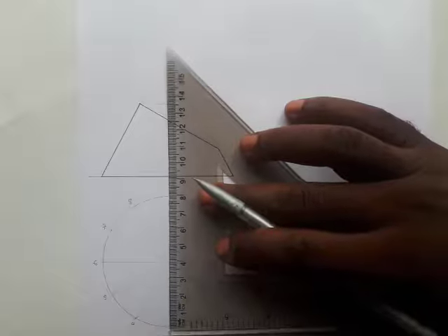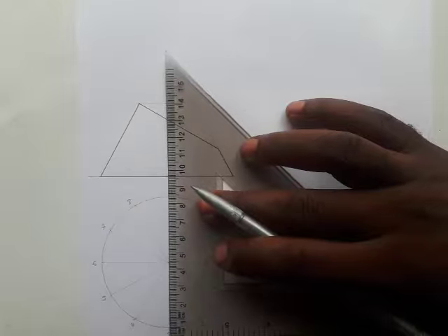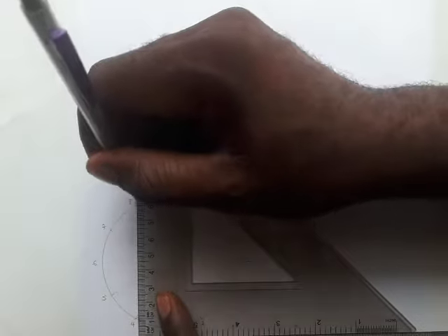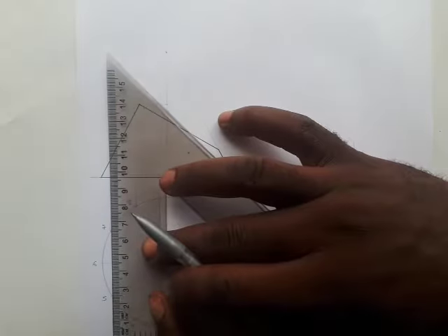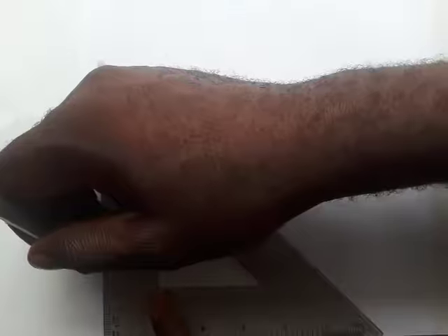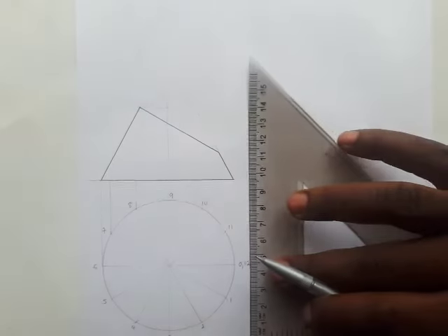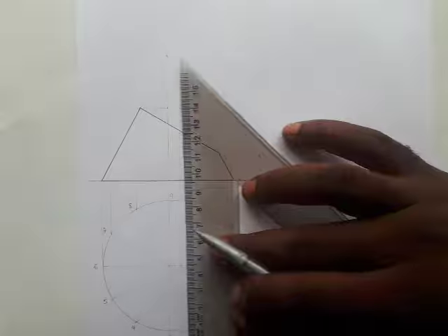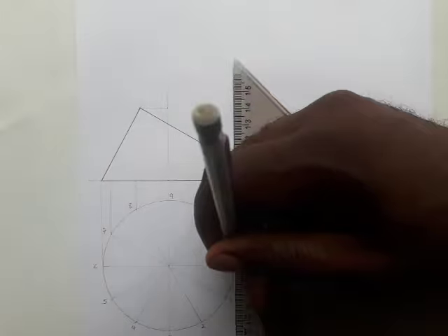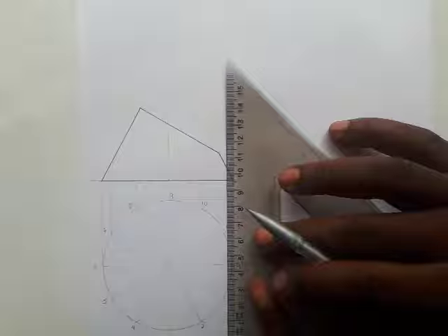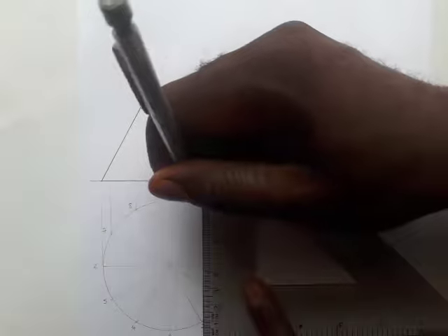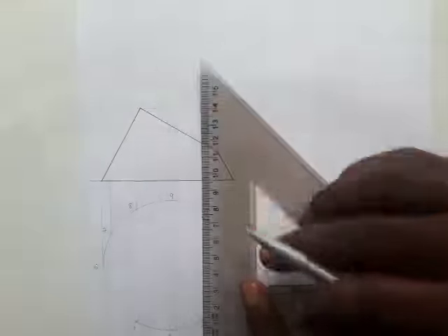So you take this center line, align your set square with the center line here, and transfer lines to 8. Draw to the base, 7 to the base. Definitely 7 on the edge will correspond, and 12 on the edge. Sorry, my hand shook. Let me take that line again. Okay, 0 will correspond to the edge already. Then 11 to the base, 10 to the base. We already have 9 drawn, so you can see.